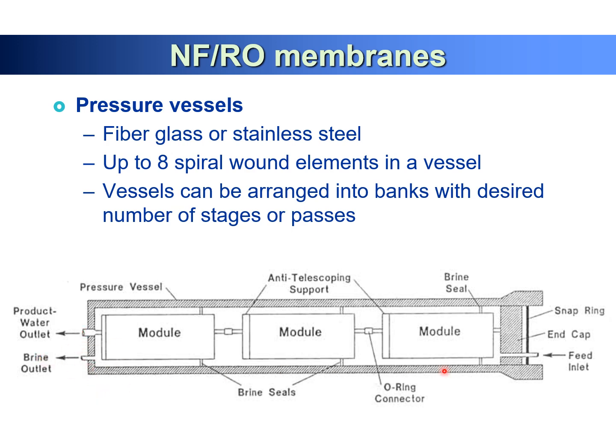This pressure vessel requires very high pressure, so you design it with very strong material, and we can put around 1 to 8 elements in one pressure vessel. Depending on your design capacity, we can select 7 elements or 6 elements.